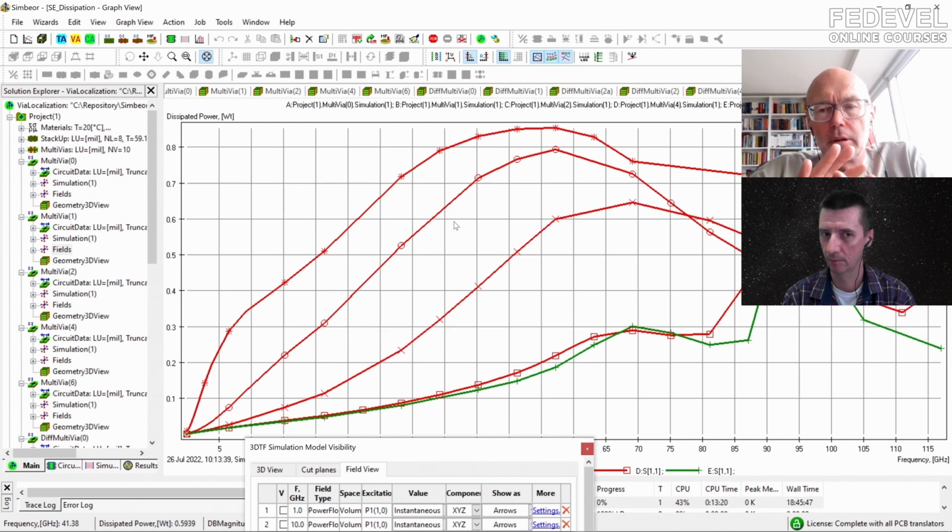In reality, this energy may appear somewhere, may get back. So planes are not infinite in the real world. There is not so much energy lost, but it will still lead to some distortion. The worst case is unpredictable distortion. So you always want your PC board designed and predictable in simulation. So you show that it works.